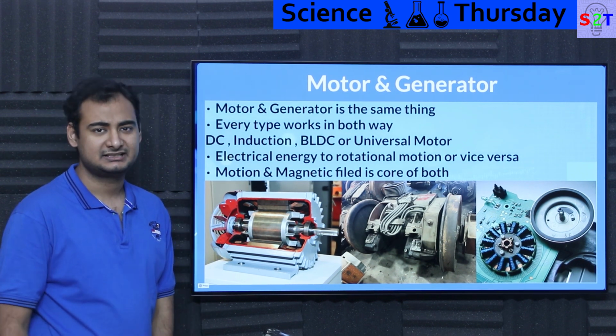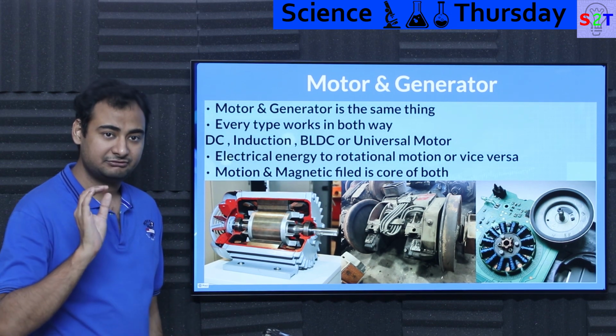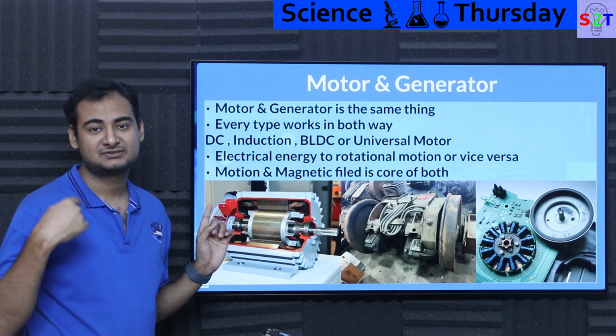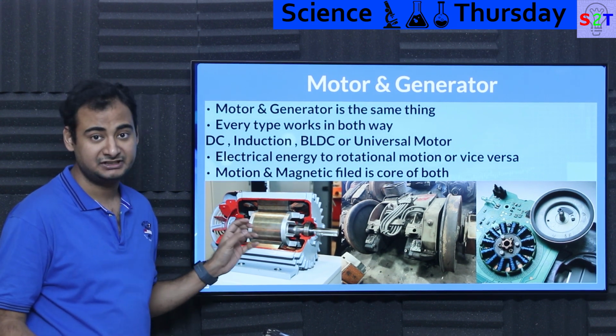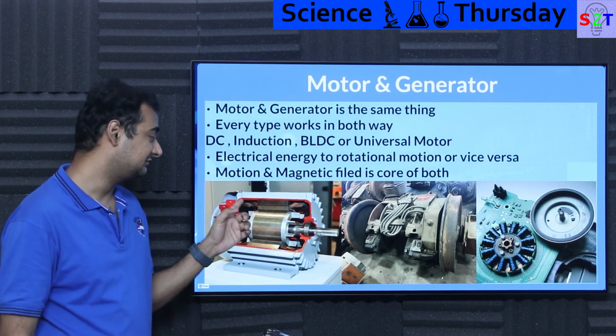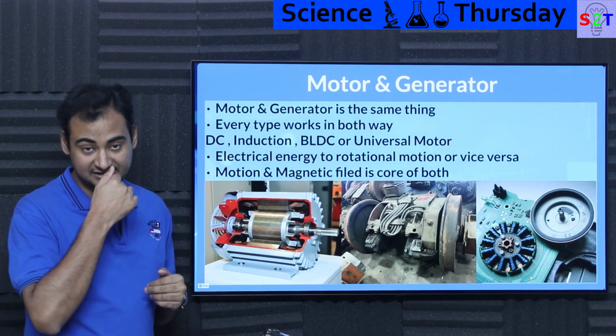Generally, some people say that at as low as 50-60 hertz you will start to get that. Or if you want to be damn sure that it produces energy, spin it at positive slip, meaning if its RPM is supposed to be 1500, spin it at 1600, and it will start to act as a generator. However, you will need a run capacitor to keep the self excitation going.